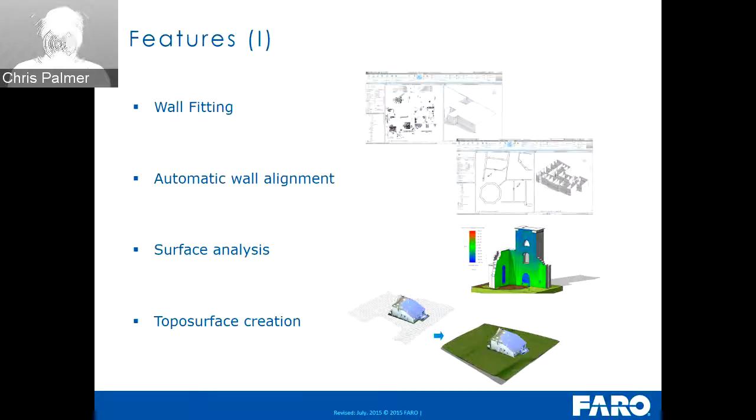And we can also use these tools for topographic surface creation and to deform shapes to more accurately represent the point cloud itself. As you can see at the bottom there, we've got some good topo surface tools which allow us to select points in the point cloud and extend the functionality of what is available inside Revit, specifically directly generating contours and things from the point cloud.